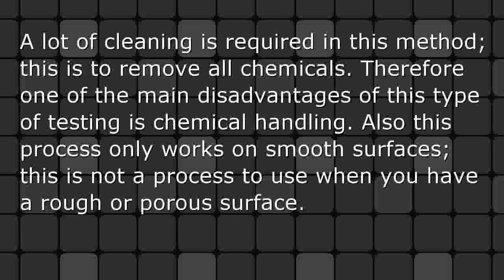Disadvantages. Penetrant testing: a lot of cleaning is required in this method. This is to remove all chemicals. Therefore, one of the main disadvantages of this type of testing is chemical handling. Also, this process only works on smooth surfaces. This is not a process to use when you have a rough or porous surface.